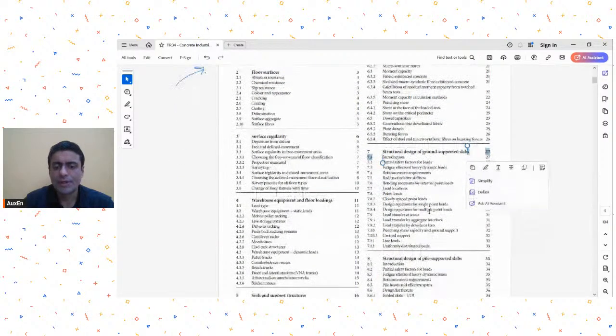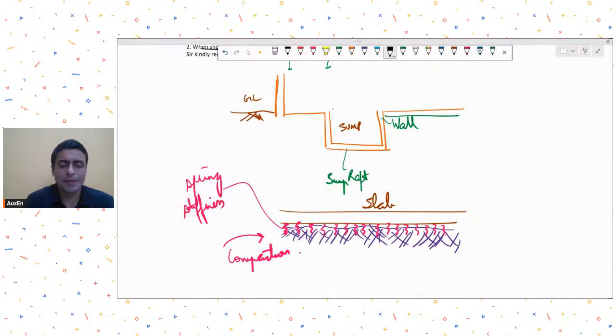This design is more like a pavement. If you can recall the rigid pavement design approach that we used to adopt, you might have learnt it in your BE Tech. That same approach is given for industrial floorings also. So the entire principle of design will depend on the nature of compaction that you are able to achieve for the earth below.